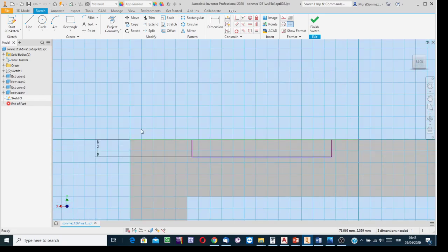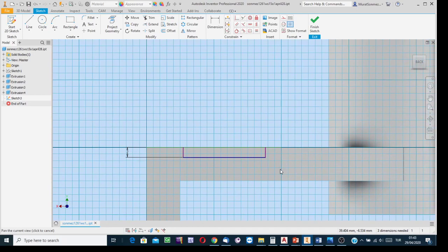And then, from the boundary of this surface, since this boundary and the terminal point of this created green line are coinciding, there is no need to create the projection of this boundary. Okay, but I need to create the projection of this intersection to be able to input the other constraint.